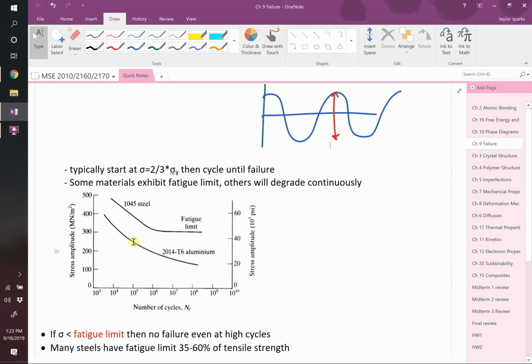If there's a nice perfect arrangement of atoms, and I bend a whole section of atoms, I'm going to mess up the perfectness of that crystal. That's called a dislocation. In some materials, those dislocations keep piling up and make them more and more brittle. Other materials are able to recover from that. Steel is able to recover from that. It doesn't have a cumulative damage effect, whereas aluminum does.